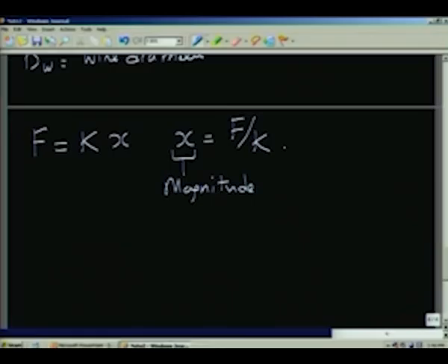So, if you want to have a reasonably small value for the displacement, one would like to go for a large spring constant, or another way we can put it is the following: if we want to measure large forces, we of course will require large spring constant. That means that the same spring balance I cannot use with infinite precision.